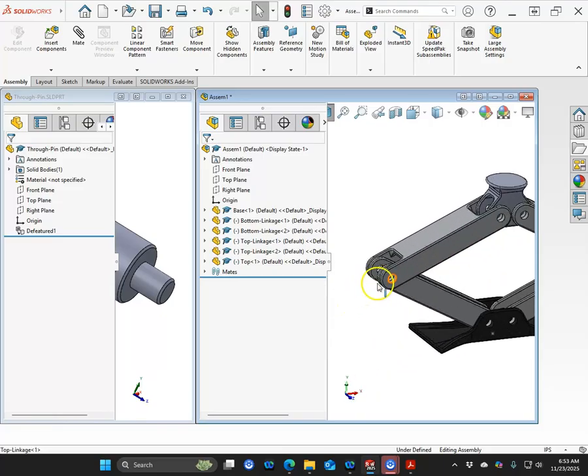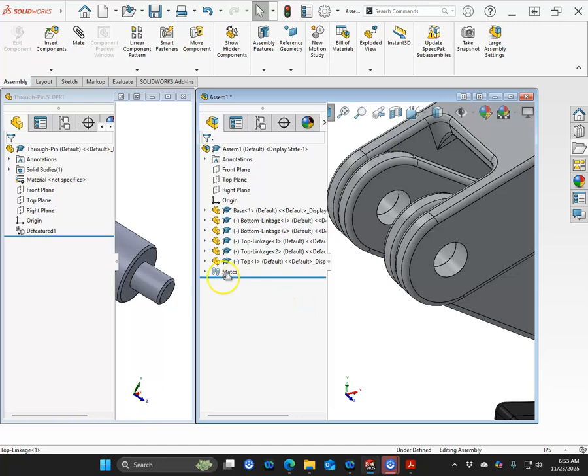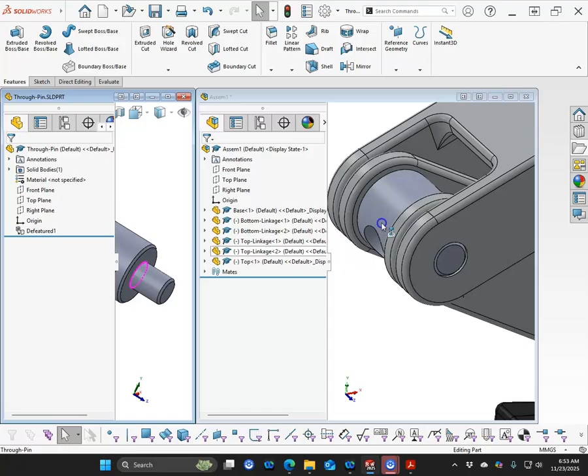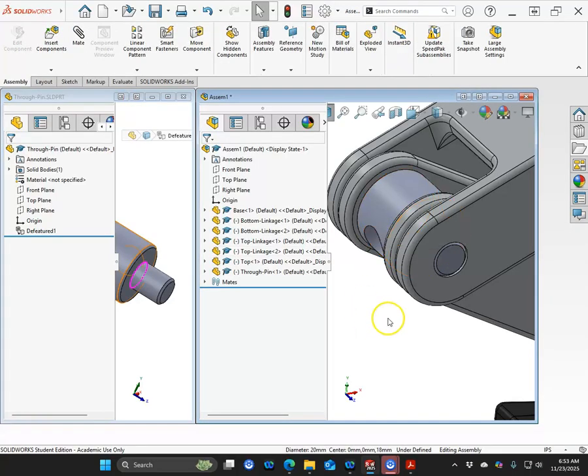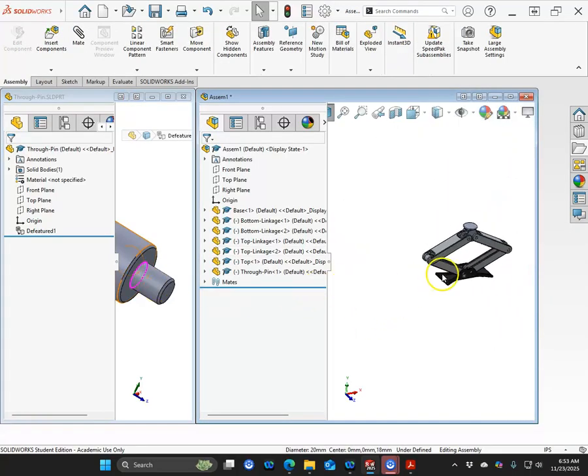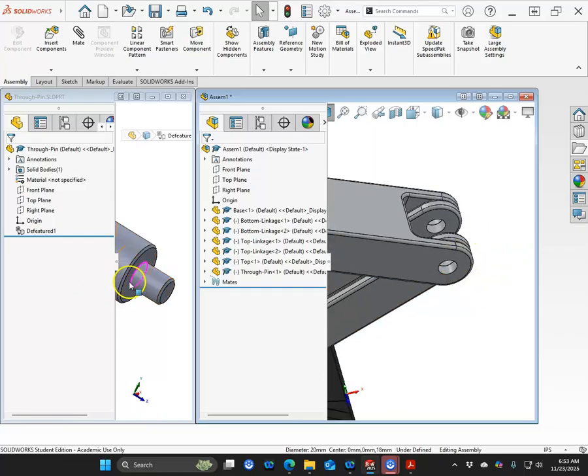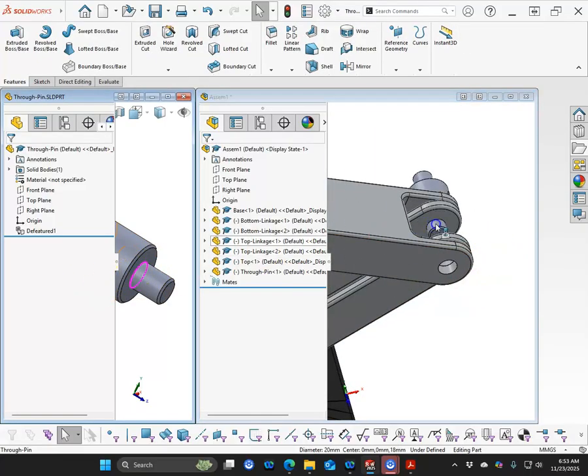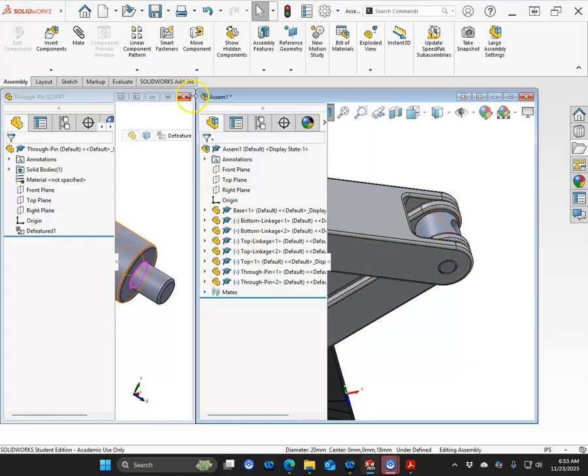So that is going to be over here. So if I select carefully from this window and drag to that window, this is going to do an automatic mate reference. So I can bring that one in, and that is a quick way of generating the mates that we need. So we're watching that push pin or that pin symbol. Always think of it as a marshmallow on the end of the stick. If I hit the tab button, it's going to reverse, and we can apply those mates very quickly.